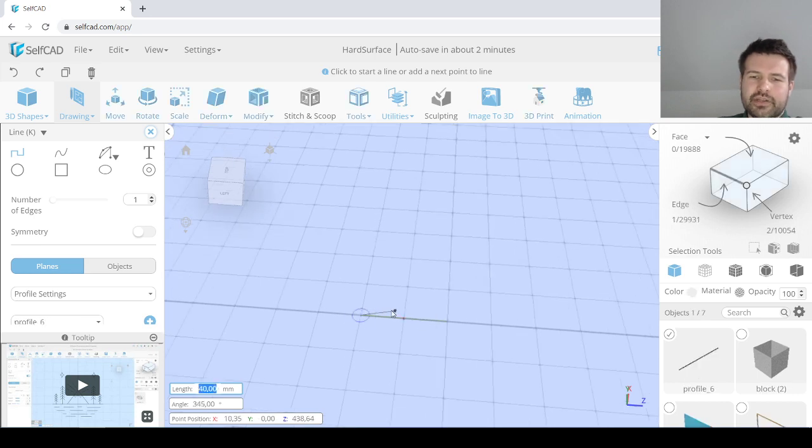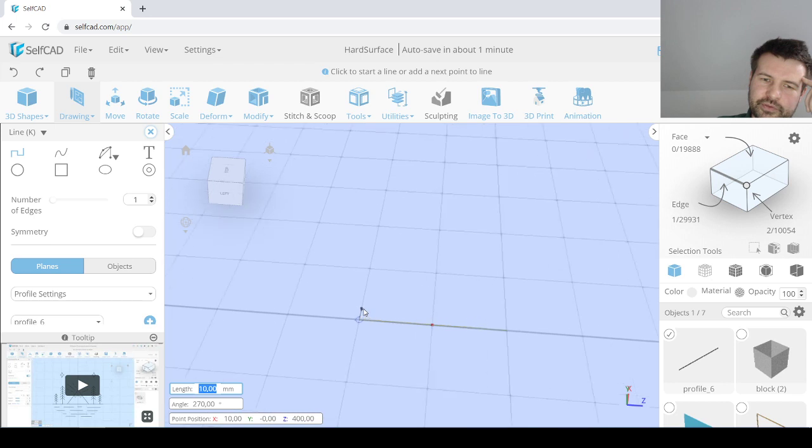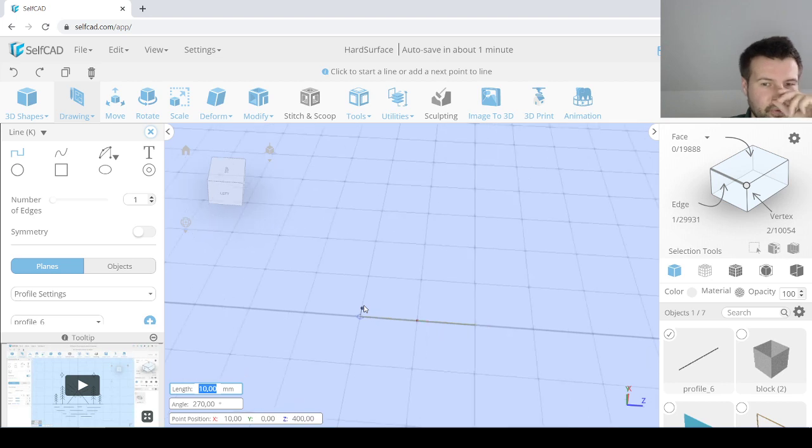But I will just show you a general method of how to think about drawing profiles. So everything that is meant to have a revolve shape will always have a profile, which will be used for the revolving part. So you need to think about taking the object and seeing it only in 2D. And if you cut it in half, this is your profile.